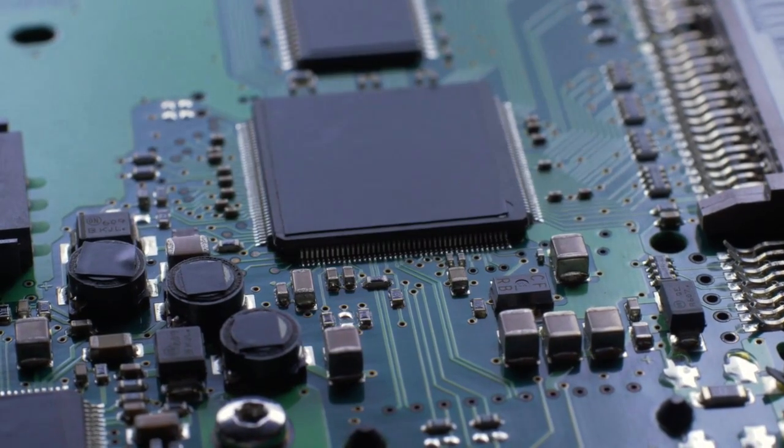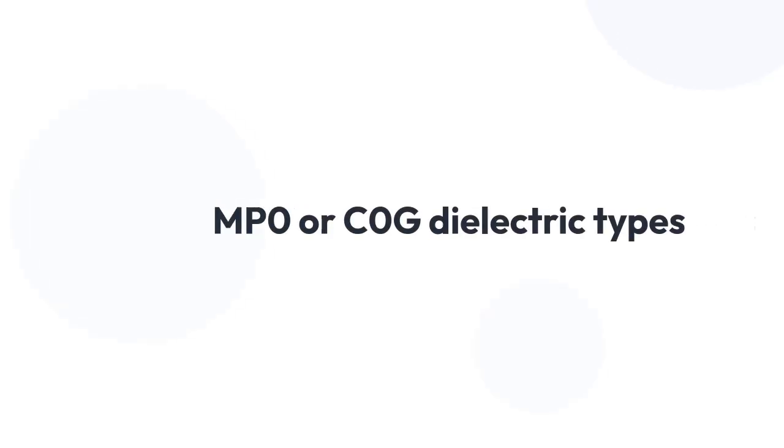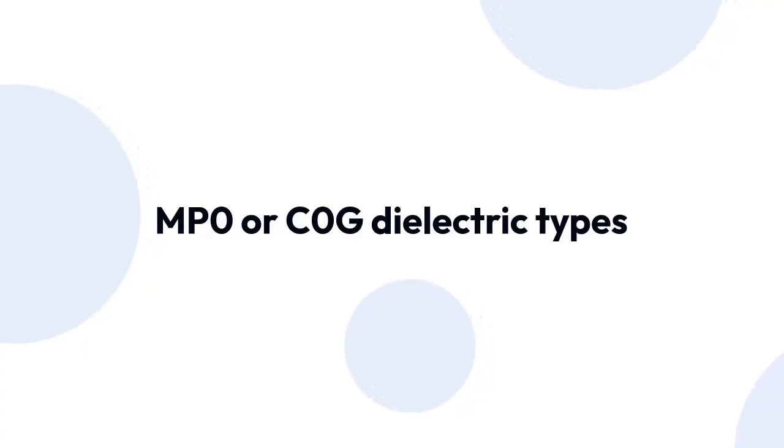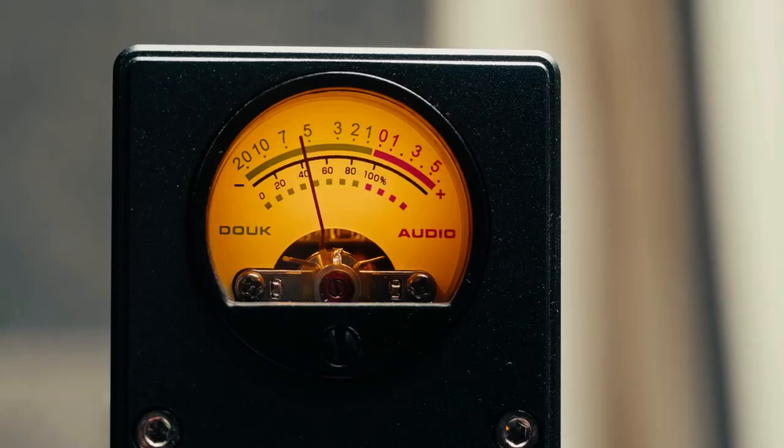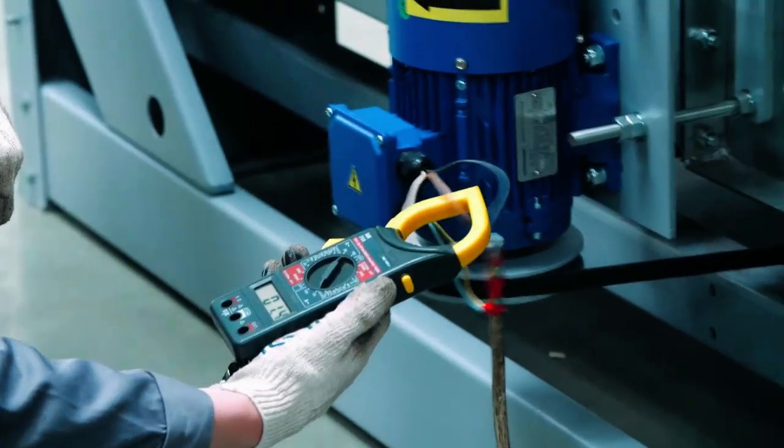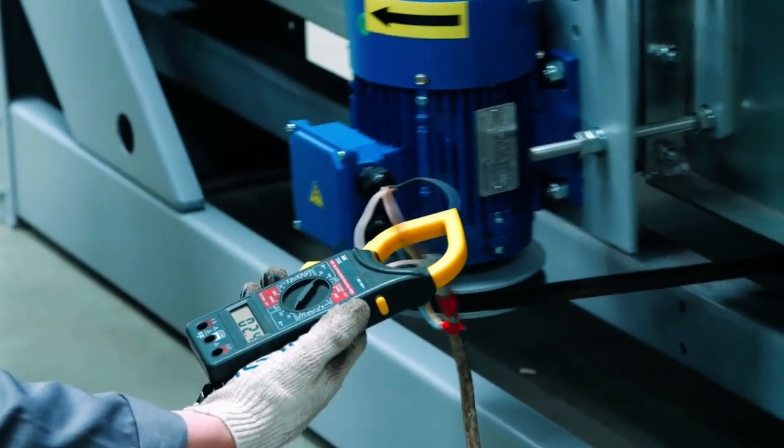Always use high-quality ceramic capacitors. Specifically, NP0 or C0G dielectric types are best. They offer excellent temperature stability. This means their capacitance does not change much with temperature variations.